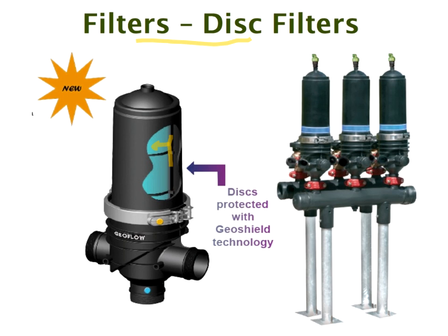We have found that we took our disc filters and we added the tributyl tinmaleate, which we call GeoShield, which is our trade name, but it's tributyl tinmaleate, which is the antibacterial material, to the plastic of the discs. Now, when this goo gets pushed in between the discs, the bacteria dies and no longer multiplies. And we're getting phenomenally good results.